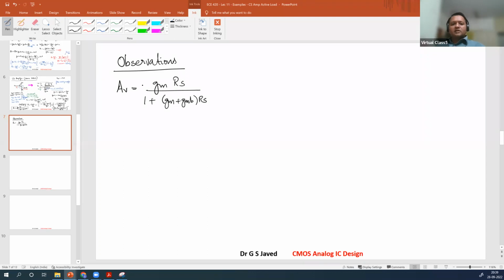So what will be your observation? First one, if your Vin equals VT, VGS minus VT will be 0. So your gm will be 0. Therefore, Av will be 0.